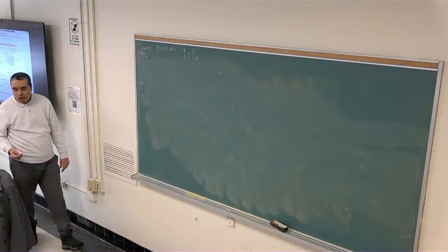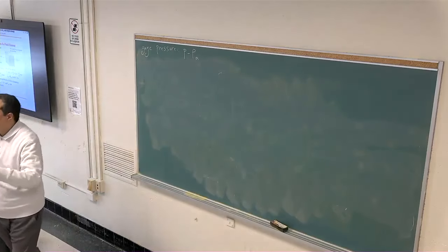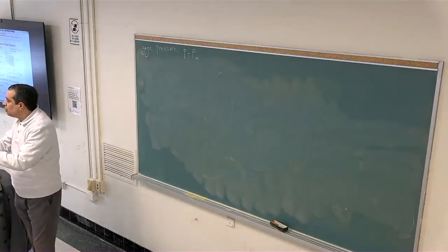Grad P has a negative sign. So when you go down, your pressure increases. In the swimming pool, if I am at 10 meter depth, my pressure is greater than P ambient. If I am at 20 meter, it is much greater. But in this room, gauge pressure is 0.